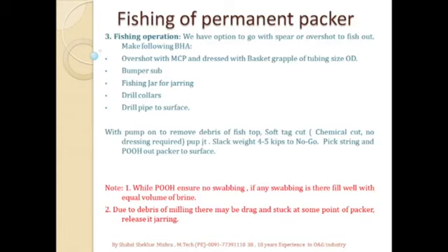Then we pick up the string and see the gain in the weight or observe some overpull. This will confirm the latching of the packer. Then we pull out the packer to the surface.